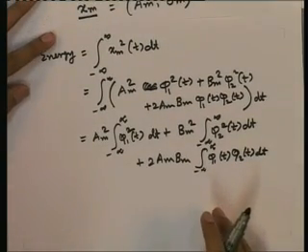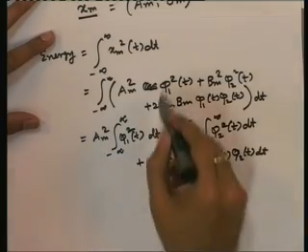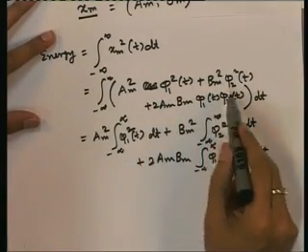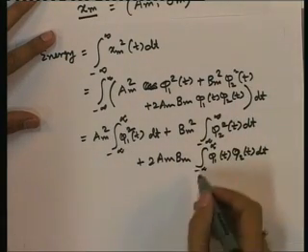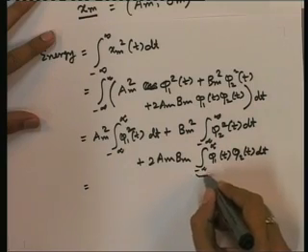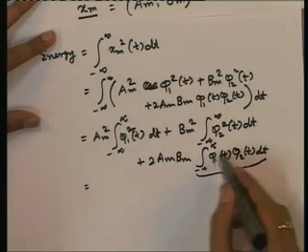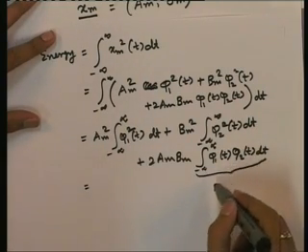We are assuming real signals phi 1(t) phi 2(t). If they are complex, we have to take mod phi 1 square, mod phi 2 square, then phi 1(t) phi 2 star(t) and so on. So, what is this quantity? We have said that phi 1(t) and phi 2(t) are orthogonal if this quantity is 0, and we have assumed that they are orthogonal to each other.